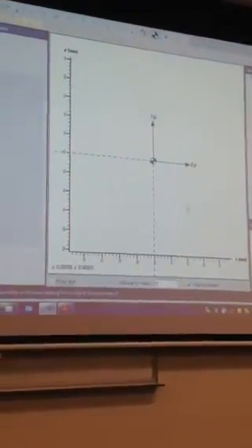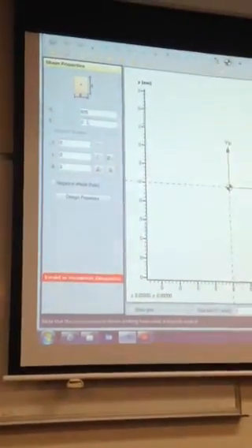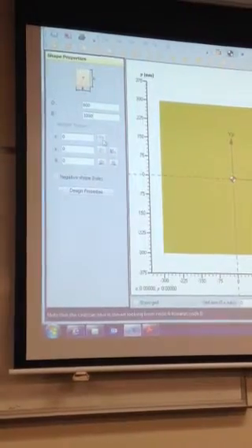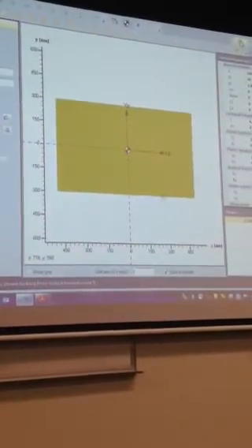If I click the little I section, that gives me the section properties, and now I can build it straight from here. Again, it's going to be a rectangle with a depth of 600 and a width of a metre. So we can OK that. Again, instead of calling it section 2, I'm just going to rename it: a 600 deep slab.